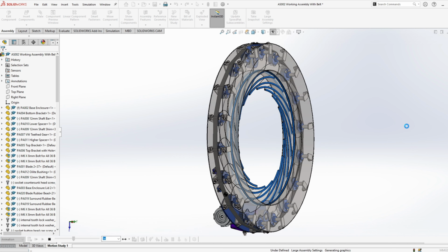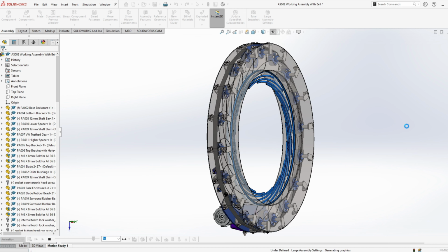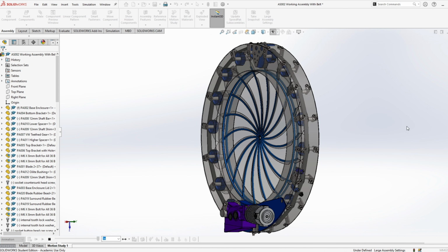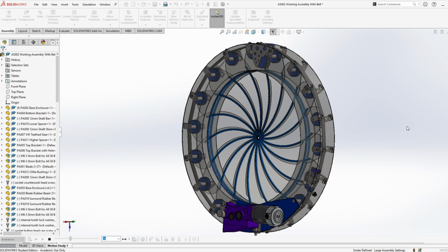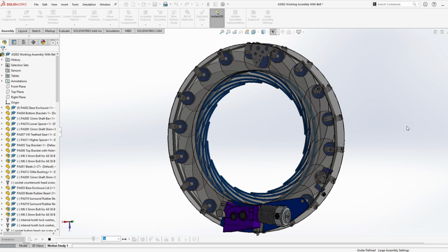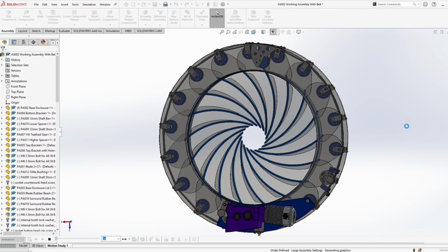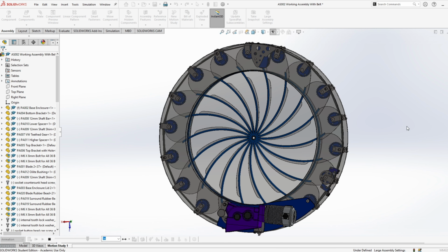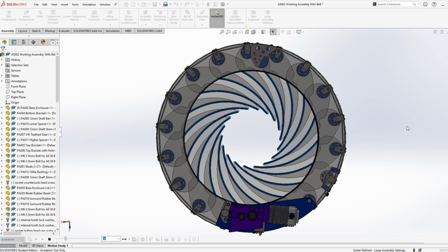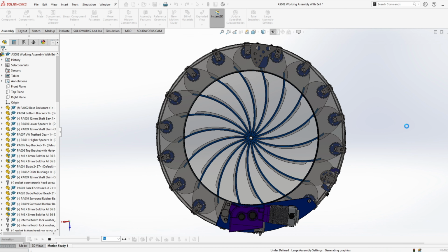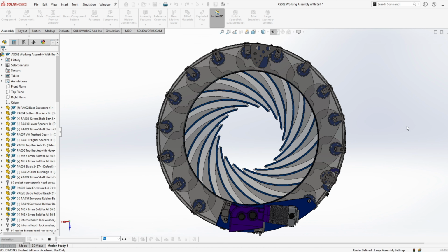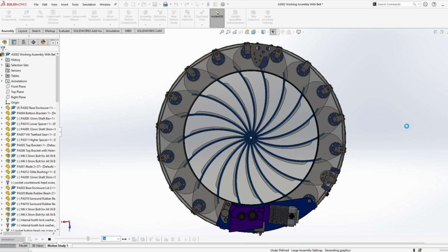Due to the glitches within the first prototype, this new prototype was redesigned completely in my head. I have now decided to drive the belt using a wheelchair motor and gearbox, rather than moving one gear and expecting the other 17 gears to replicate the same movement instantly. No matter how much tension was applied to the belt throughout prototype 1, there would always be unwanted spring between the driving gears due to the excessive rotating force needed to move all of the diaphragm.